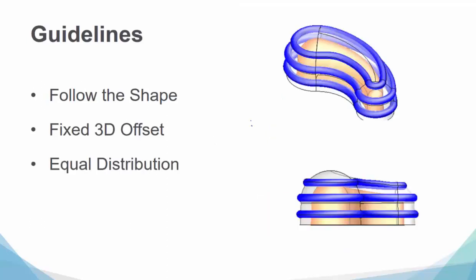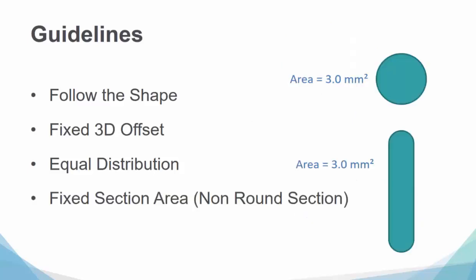So as I build up water lines, I may see something like this. There at first looks like maybe that was intersected by planes. Maybe the faces were offset so they could hold the distance, and based on that intersection, I found exactly where the center of those water lines should go. But in the profile view, you see how that water line has drifted down a little bit. We want to keep it equally distant, 3D, away from the part, and equally distributed as it works its way around the part. All right. So there are some design considerations there to look at.